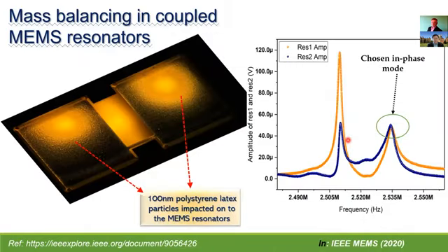Now, the other important thing to notice in these resonators is that when particles get deposited on the resonator surface, it fills quickly. So if the concentration of the particles is very high, the sensor lifetime will be reduced. That is, we will have to replace these resonators immediately. So one thing we did, in order to test the lifetime of these sensors, is we tried initially impacting 100 nanometer polystyrene latex particles at higher concentration onto these coupled MEMS resonators for 5 minutes on the first resonator and for the next 5 minutes on the second resonator to see what would happen in the coupled MEMS